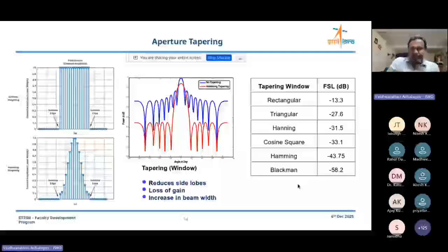So the main advantage of this phased array is that we can do beam shaping. We can alter our own side lobes. These things are not possible with the mechanical antenna. So when n elements are excited uniformly, we have a beam like this, which we call a normal beam, with the first side lobe level at 13 dB down, and all the other lobes are dying down.